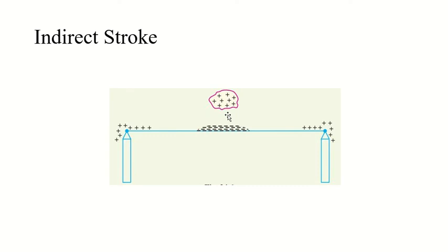The negative charge, however, will be only on the portion of the line right under the cloud, and on the other places there is nothing, you can see. But again, see on the corners, right? We are seeing the positive charges. The positive charges leak slowly to the earth via the insulators.